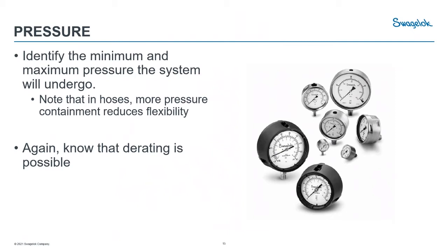Also think about the working pressure of the product compared to its burst pressure. Then you can choose which product is best suited for your system. Again, know that derating is possible, so if your temperature increases, the pressure rating will decrease.